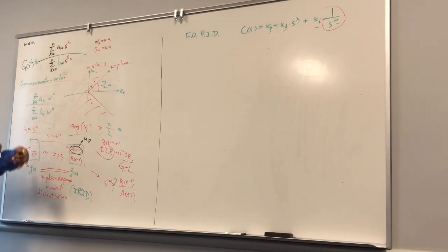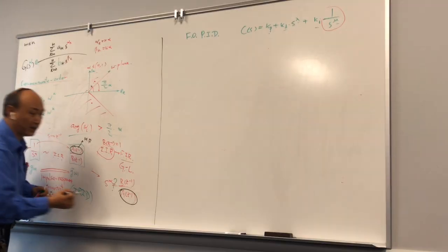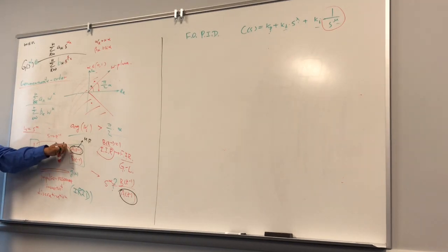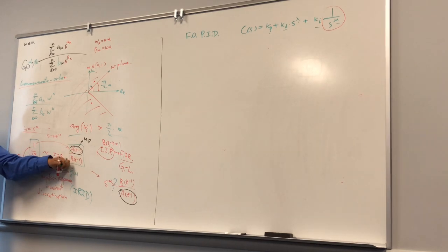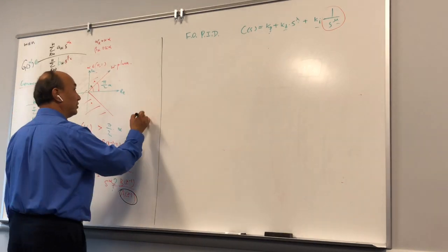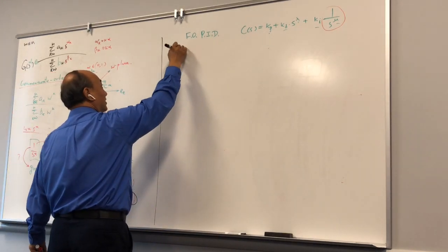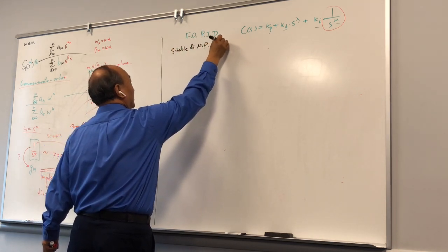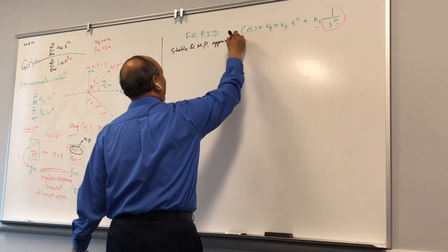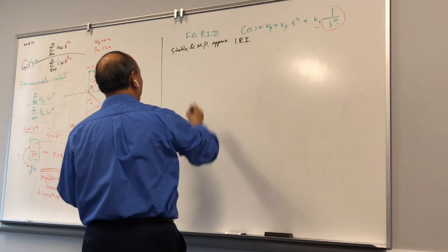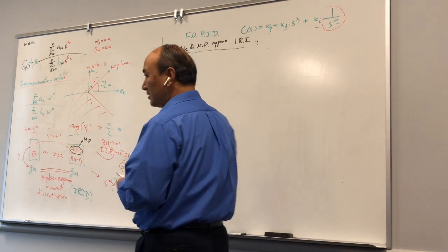Otherwise, if you do the inverse, it becomes unstable. So how can you approximate and guarantee that it is stable, of course, minimum phase? A stable, minimum phase approximation, and basically also impulse response invariant. How to achieve that?